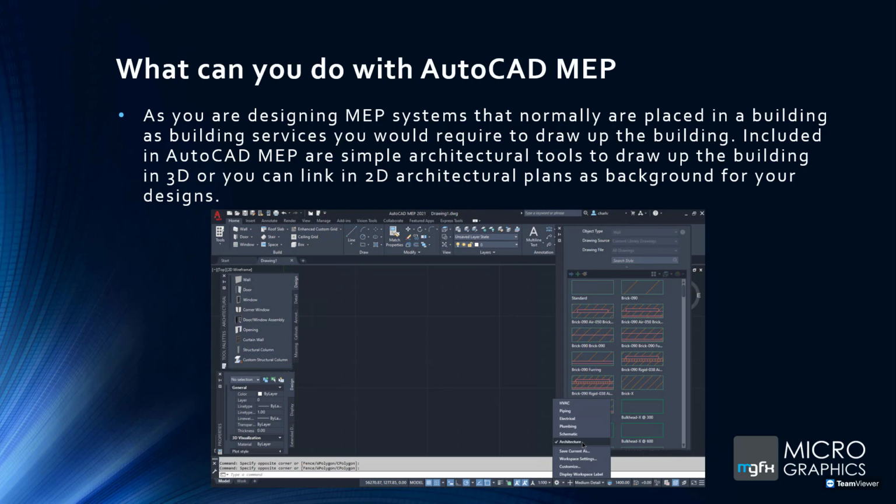You would just see the 2D plan of your architectural floor plan, and above that, your ducts and pipes and electrical information. Looking at that 2D model from the side, you'll see at the bottom is your plan, and the ducts and whatever are floating. In that case, you can import again, or insert a section or an elevation of the building that you received from the architect, and that will appear as a background so that your ducts aren't floating.